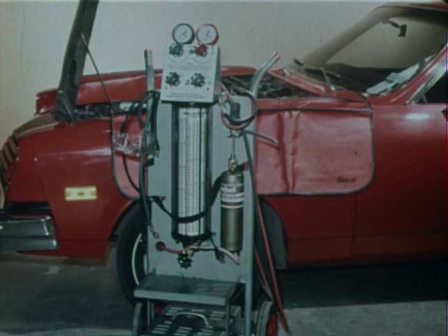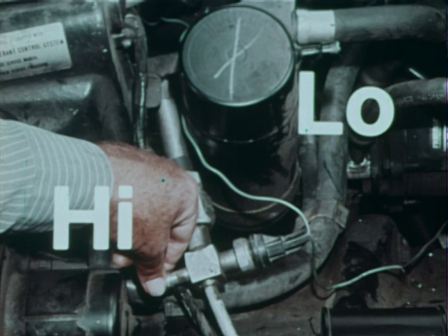In order to add refrigerant to the system while performing the refrigerant quick check test, use the following procedures with a portable charging station. With the engine off, remove the caps from the gauge line fittings on the vehicle. The high-pressure fitting is located in the high-pressure liquid line opposite the compressor discharge pressure switch. The low-pressure fitting is located on the accumulator.